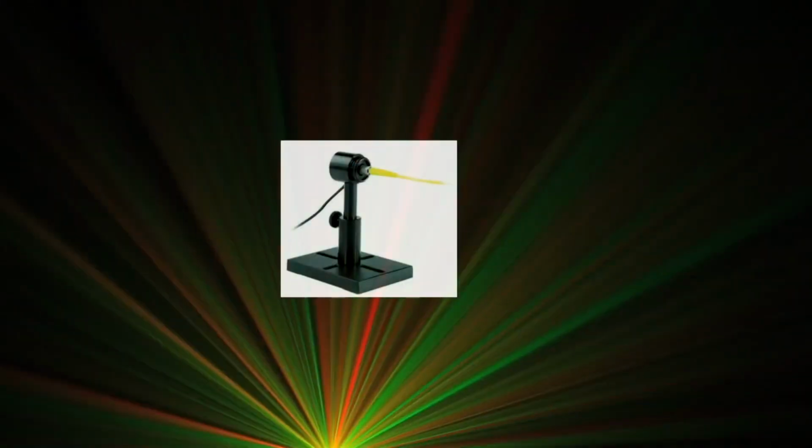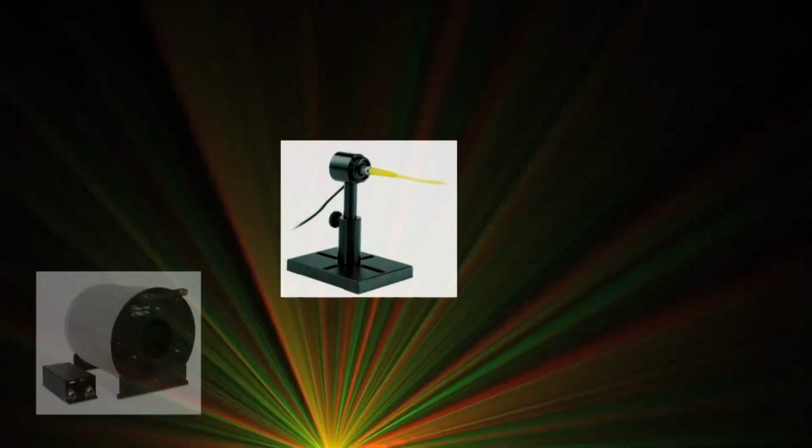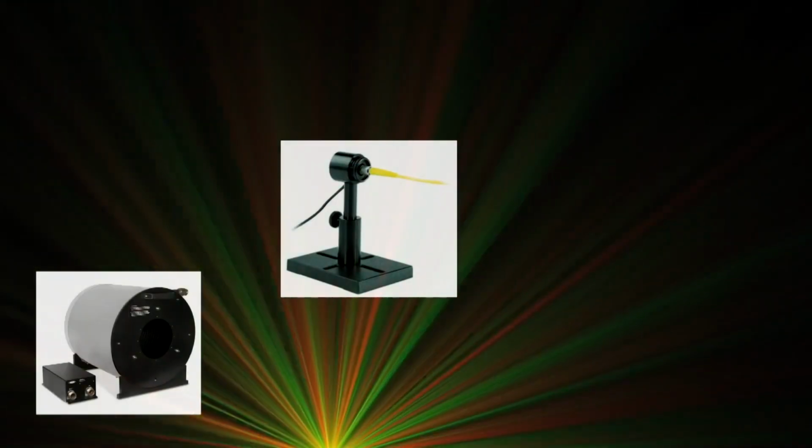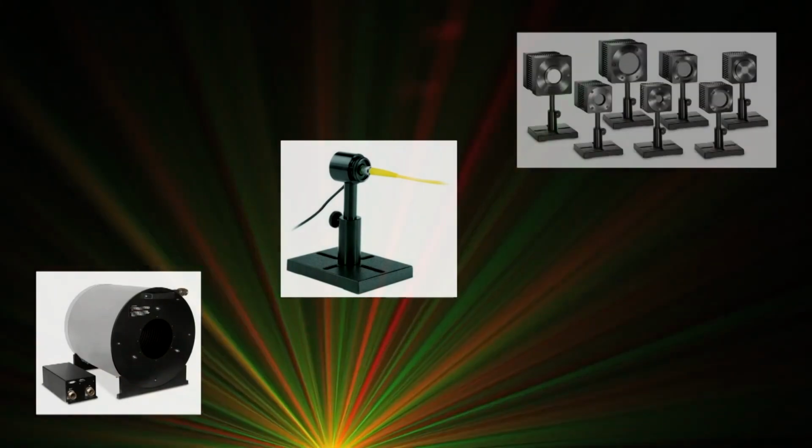Many industrial laser systems use a combination of the two, where an operator periodically fires the laser into a sensor, and the reading from that is used to automatically self-calibrate a small sensor inside the system near the laser, for example. Ophir offers sensors that can measure a few picowatts, 120 kilowatts, or anything in between, so all options are open.